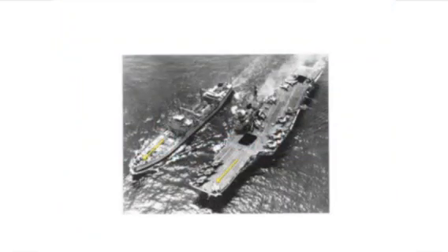In the case of two ships, we see two ships here sailing toward us, toward the lower left-hand corner of the picture, and this represents, with those two arrows, the speed of the water passing on the outside of the ships. A bigger arrow is the water passing between the ships. Because of the shape of the ships, the water has to narrow down through a narrow channel and has to flow faster between the ships than it can flow on the outside of the ships. And what that means is I get, in both cases, a force that is pushing each ship toward the other one.